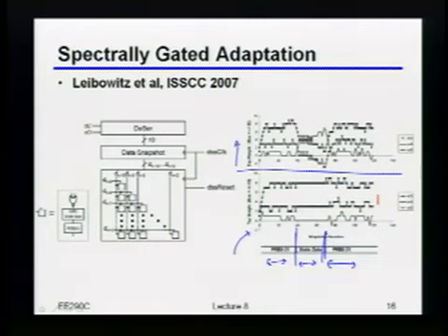Yeah. As long as you are doing the online tracking, even if you go into some not so good status, you're still fine, right? You can see that you're going back to. No. So here's the problem. You said that as long as you're doing online tracking, then you should still be OK, right? Well, here's the problem. Those data bits right there have really bad equalization settings. So you mean the first few? Exactly. The first few bits after I start getting real data have really bad equalization settings, right? Which means that I'm very likely to make mistakes, and if I've made a mistake, that's it. I've lost my 10 to the minus 15 bit error rate, or in fact, even people want 10 to the minus 17 now, because there's a fixed number of errors you want per unit time, and if you're going faster, then the error rate just keeps having to go down.